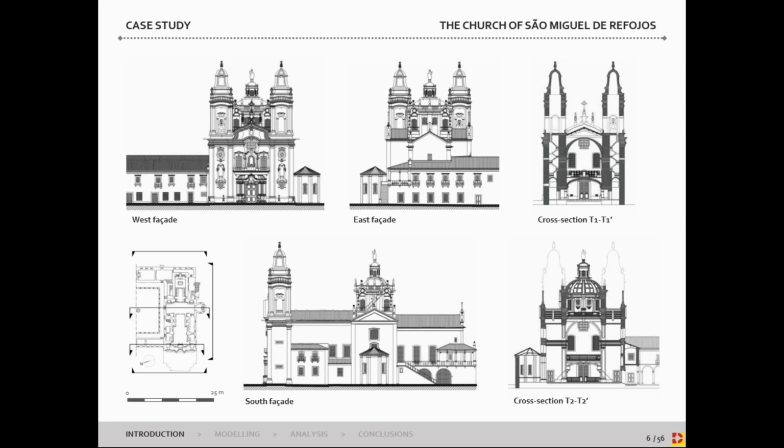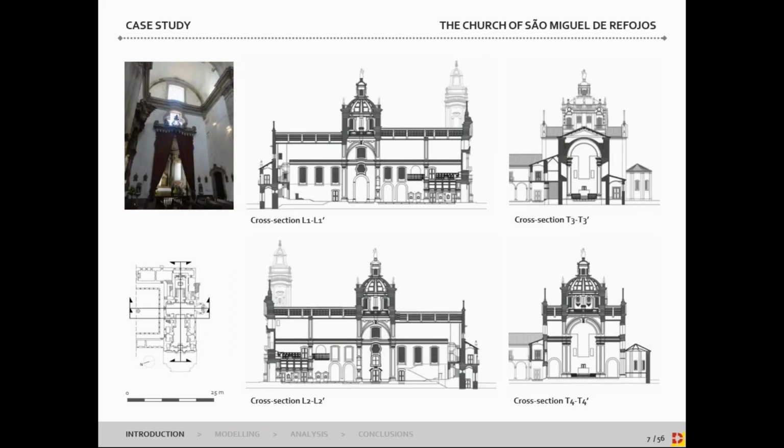The transept also connects with the lateral chapel located outside the main body of the church. And now this final part, the chancel, made up of a presbytery with the main altar, and it also has lateral annexes, in this case at a lower level in relation to the floor of the church. The nave, transepts, and chancel are covered by gable roofs with ceramic tiles, and the structure of the roof on top of the nave is the only one accessible. We could see in the inspections that it consists of timber trusses oriented in the shortest direction.